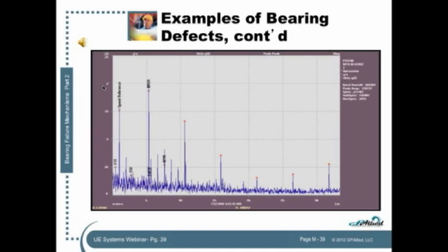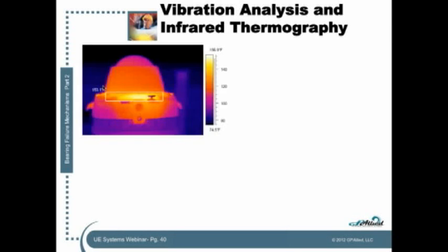Now, the imbalance does happen, the misalignment happens, but usually the misalignment happens after some type of maintenance event and we didn't get it lined up right. It's not like misalignment happens just out of the blue. And imbalance happens usually when it's been a while since we've let the turbine cool off, and we get this bow in the rotor, which kind of acts like an imbalance and a misalignment all at the same time. These are not so rare that we shouldn't worry about them, but they're certainly not as common as water in the turbine lubricant oil. Water in the lubricant oil probably is the worst culprit of all turbine bearing failures, at least rolling element bearing failures.